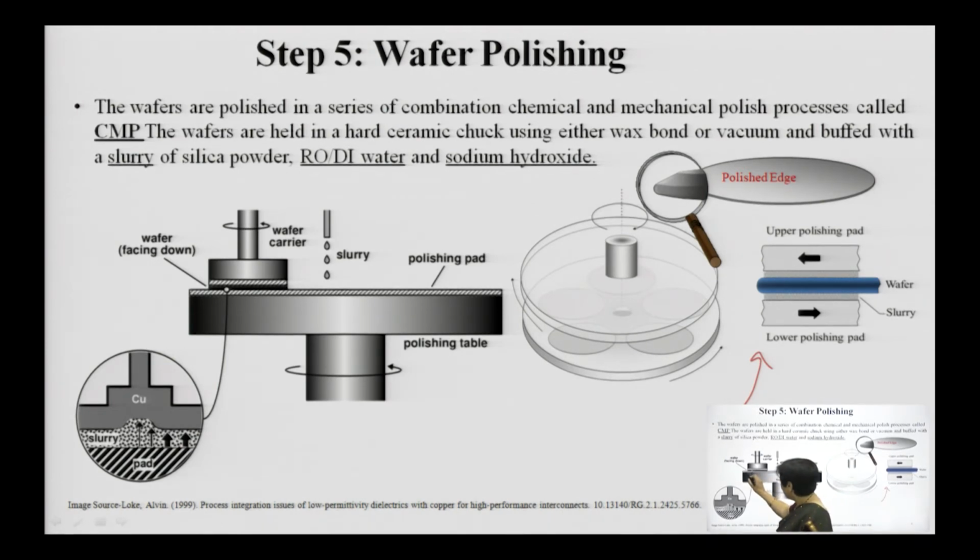The wafers are placed on the polishing pad, and there is continuous slurry which works as a lubricant. It is just like when you are polishing your floor, you are putting some slurry of calcium carbonate on it, and that polishing machine revolves. So similarly here also, these are the polishing pads which rotate without creating abrasions onto the surface. With lapping you already have some coating onto it. The same thing is being used over here.